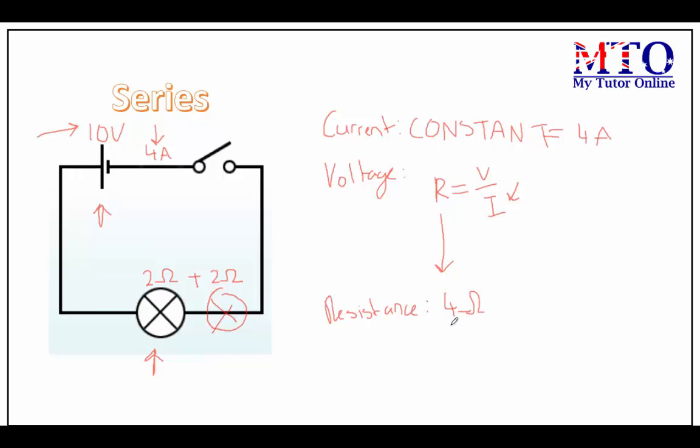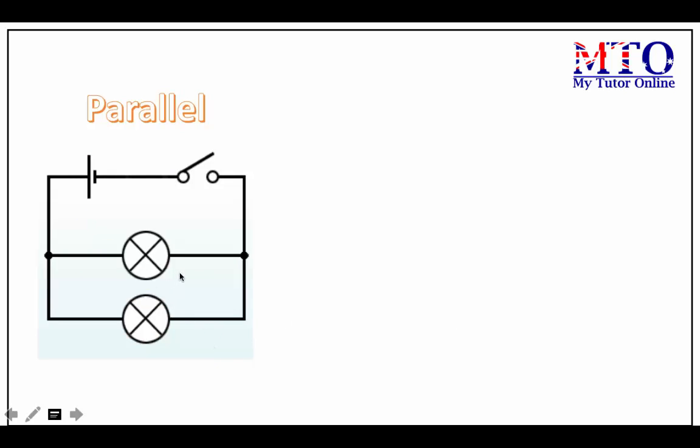So let's take a look at a parallel circuit now. There's a clear distinction between a series and a parallel circuit, as we can see that there is a break here and here. These breaks indicate that the circuit is indeed parallel. So let's assume that we have a current of 5 amps here and resistances of 2 and 2 ohms. We will take this time to find the voltage of this power source to give you a better understanding of how this works.